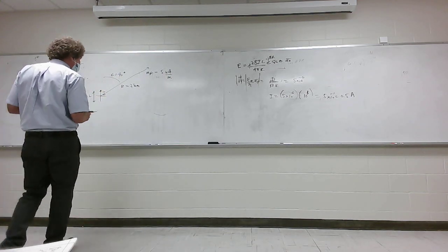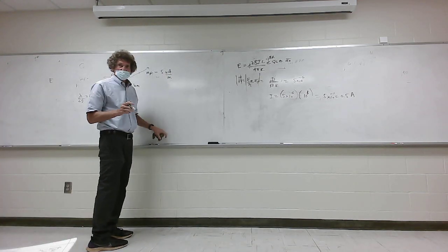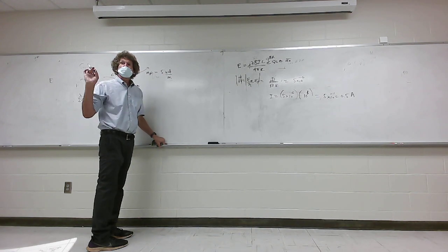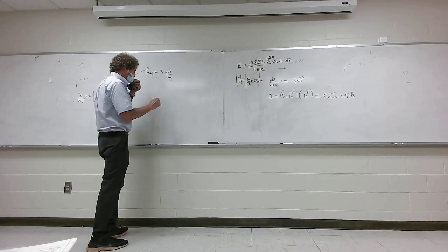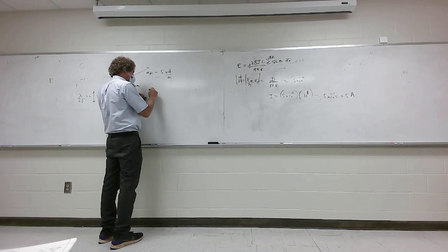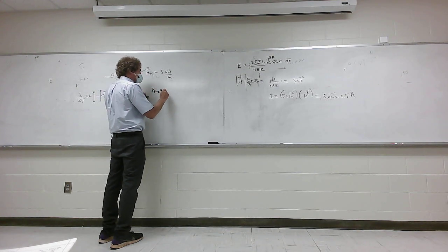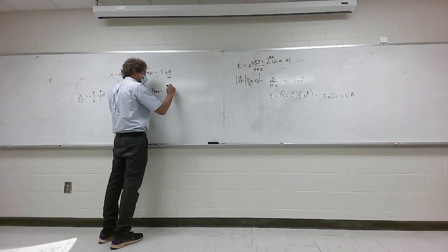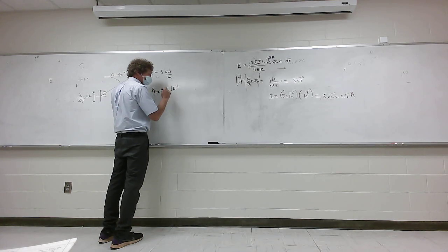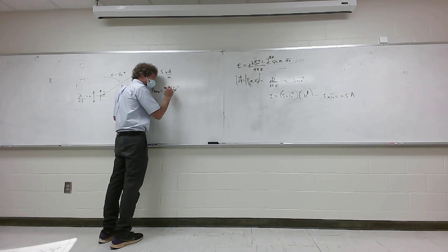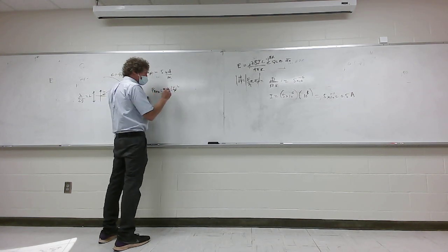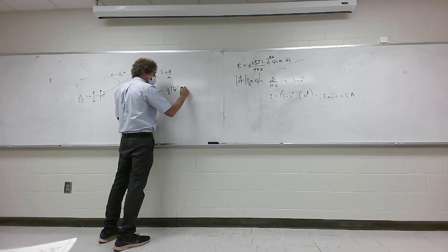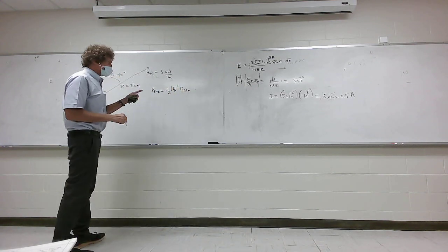So once I have I, I want the power, right? Please hear me now. It's a short dipole, right? P radiated is equal to 1/2 magnitude of I squared. That's the peak I, by the way. That's not RMS. I squared times R rad. The only thing I don't have is the radiation resistance.